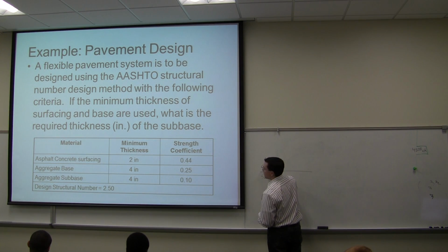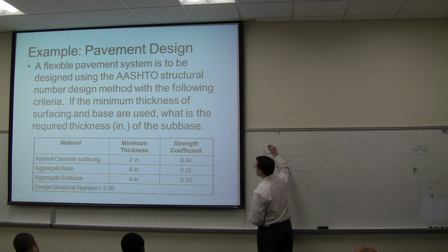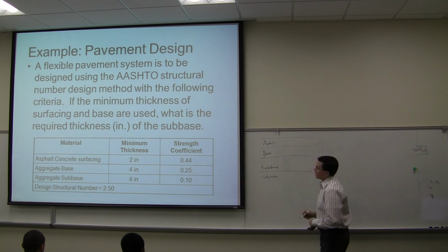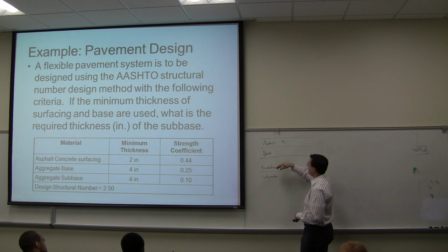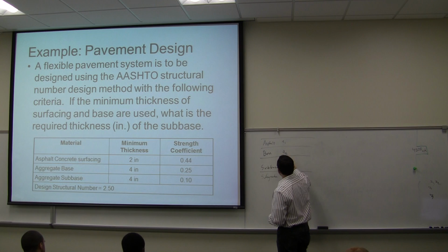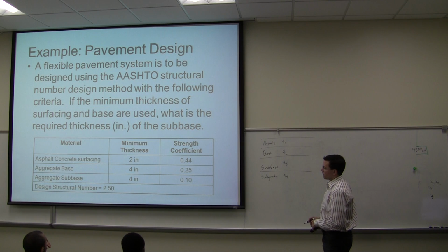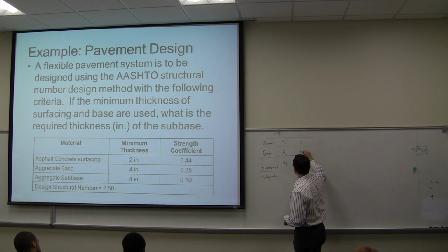We have subgrade, subbase, base, and then in this case we have our asphalt. Each of these has a coefficient, A1, and we always number from the top with the asphalt layer being A1, A2, A3, and A4, which actually we don't have a subgrade strength. So we just go 1, 2, 3, 4, and then we have the depth of each of these, D1, D2, and D3.